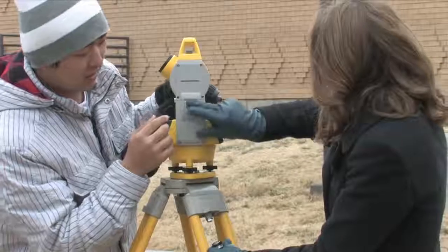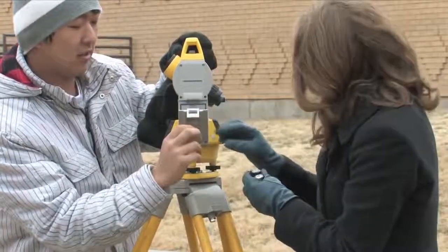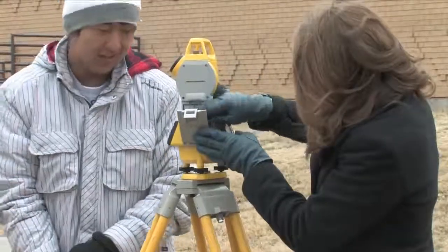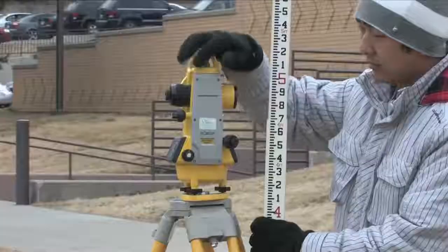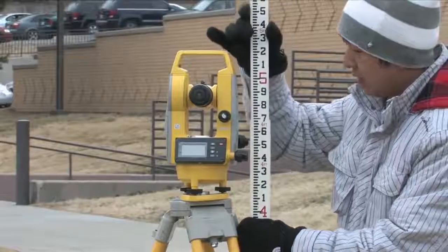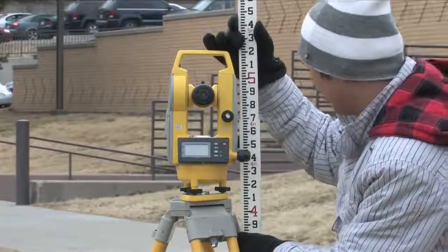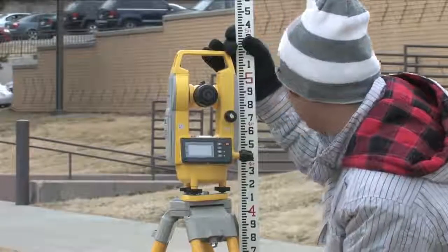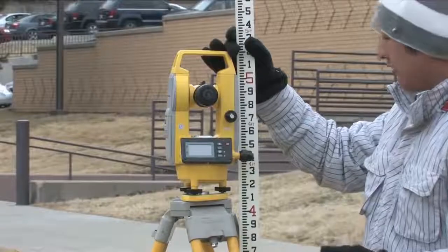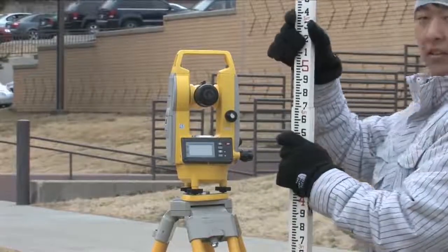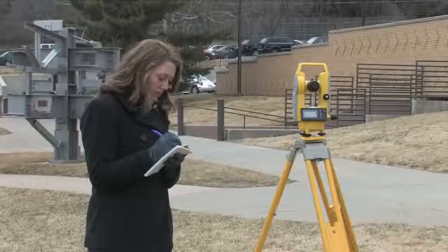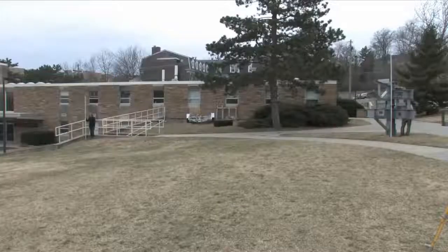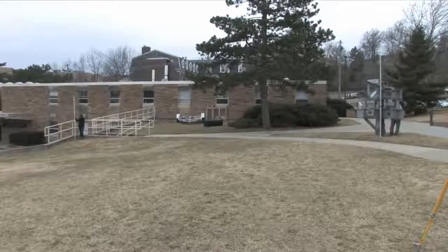Next, open the battery door located on the side of the theodolite and insert the 2 C batteries located in the case, paying close attention to the positive and negative polarities. Finally, to complete the instrument setup, record the height of the instrument by using either the rod or a tape measure to measure the height of the instrument from the ground up to the gray line located on the side of the instrument as demonstrated. Record this value in the field book, in this case 4.80 feet. It is a value that we will refer to again as we complete this portion of our survey.